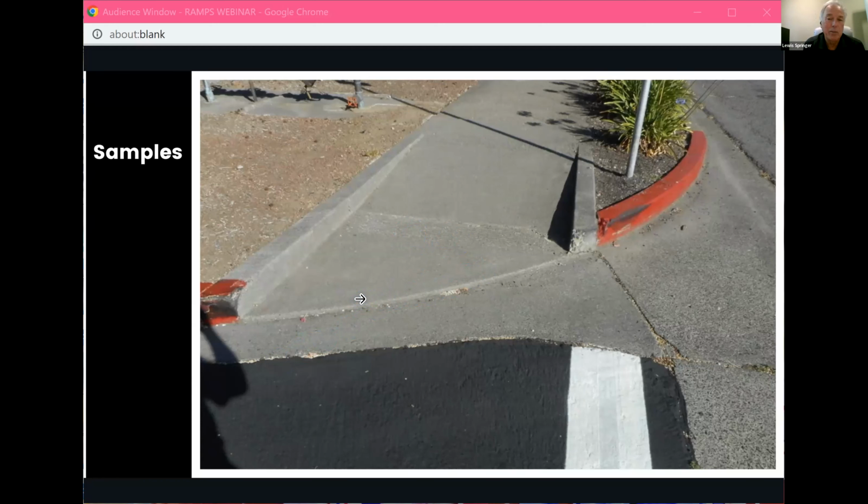I've seen this done a number of different ways, where the curb ramp itself is sloping from the top where it meets the sidewalk down to the gutter line. And in doing so, that actually makes it not compliant with section 406.5.6, which requires that grade break be perpendicular to the ramp, because all of a sudden the curb ramp is a skewed slope.